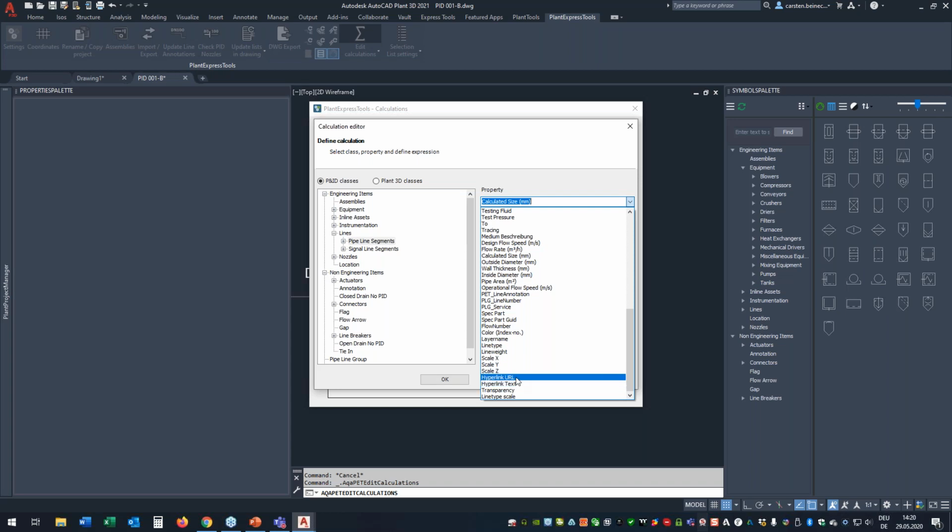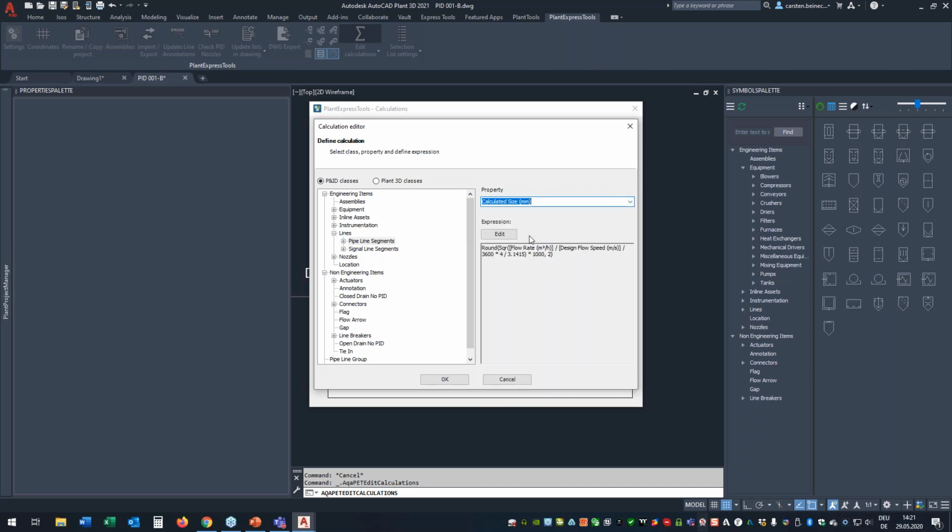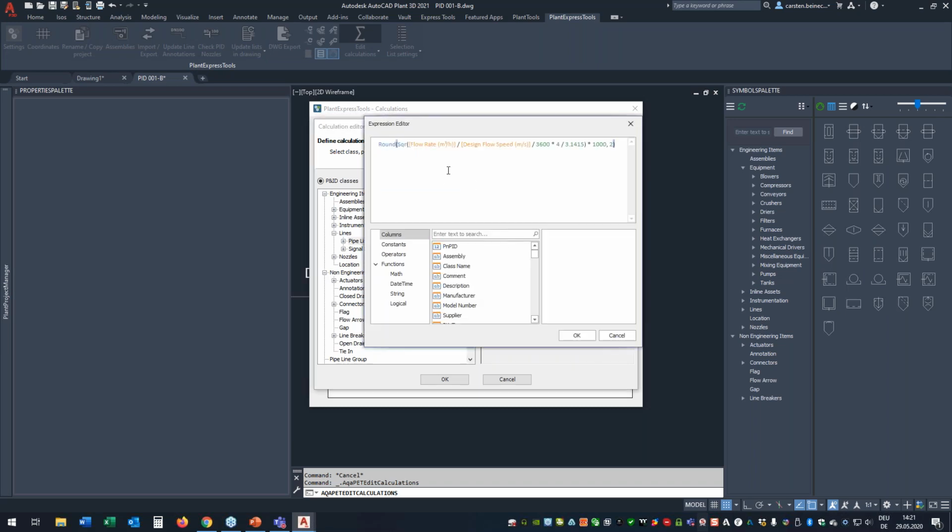So if they type in a tag for an equipment, assuming it's an existing equipment and there is documentation, then we type in the tag, and based on that, the hyperlink is calculated. So when they create the PDF, they can click on the equipment or the equipment list for that piece of equipment and a PDF opens, for example. So that's another possibility. But this is the property I'm calculating, and this is the formula.